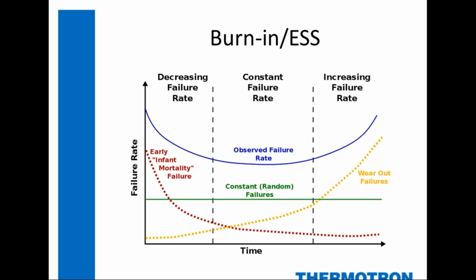This graphic here is what's called a bathtub curve by reliability engineers, and it determines the failure rate of a population of products. Many products have a statistically higher failure rate during the first part of life, which we call infant mortality, and these are obviously failures you don't want your customer to experience. These failures are generally due to errors in material or assembly procedures during manufacturing.